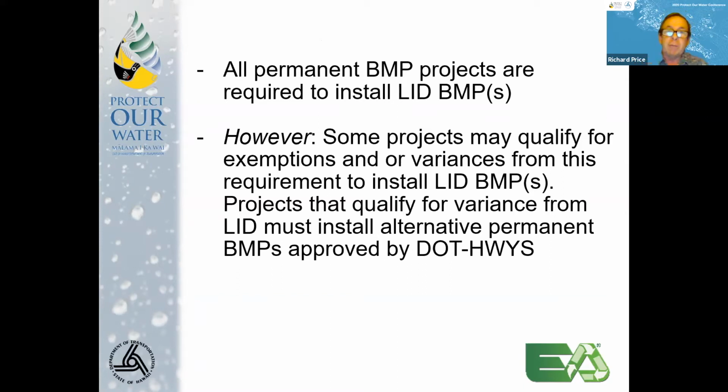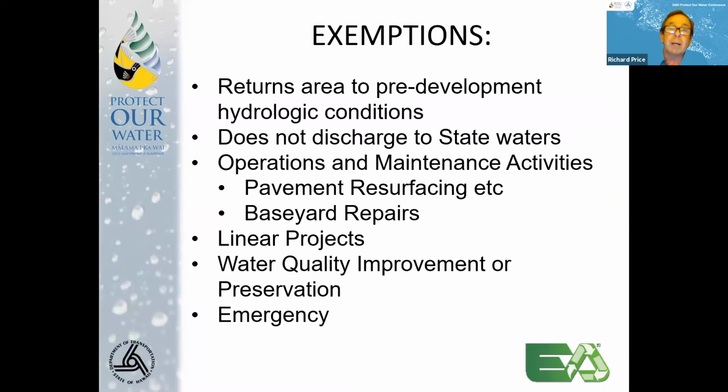So, as I said, if you reach the trigger, you're required to install LID. However, some projects may qualify for exemptions and variances. And that's where we revert back to more traditional permanent BMPs, which may be proprietary devices or some other form of treatment that's appropriate. So in terms of exemptions, if you have a project that is returning an area to pre-development hydrologic conditions, if you are not discharging to state waters, and my understanding of the interpretation of state waters in Hawaii is that pretty much every square inch of land on the islands is state water.